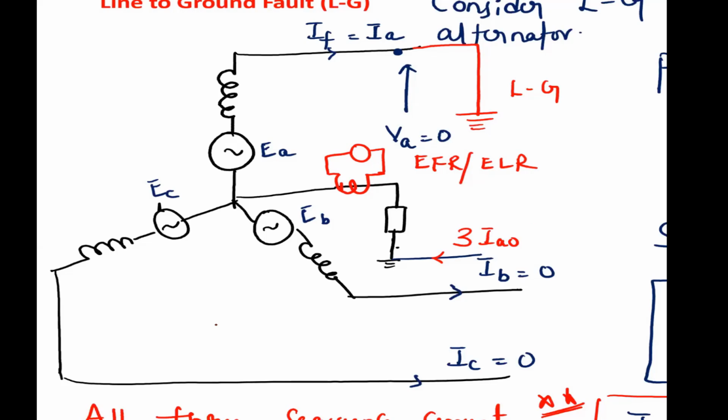So how the fault current will flow in the system in case of an LG fault, I am telling you. It starts from the source, goes through the fault, through the ground, and again through the ground it will enter and flow through the system. This is how the fault current will circulate, these violet lines. Understand? Definitely this fault current will flow through the neutral as the return path. So here the relay will sense the fault and it will trip.